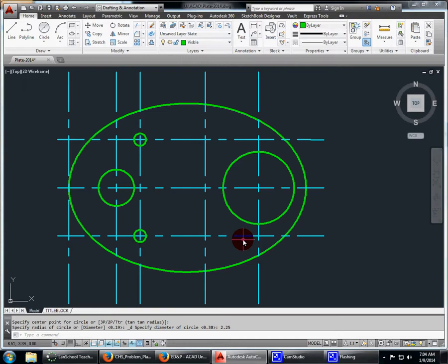And then now we have the big, well, it's often called the C, or the hot dog in the middle. And students will sometimes freak out. But what I'm going to do is I'm going to look at it. I'm going to go, okay, well, I know right here I have 2 circles of the radius. So let's go do those first. They have a radius of 0.38. Enter key, pick my point, enter key again because they're both the same size.